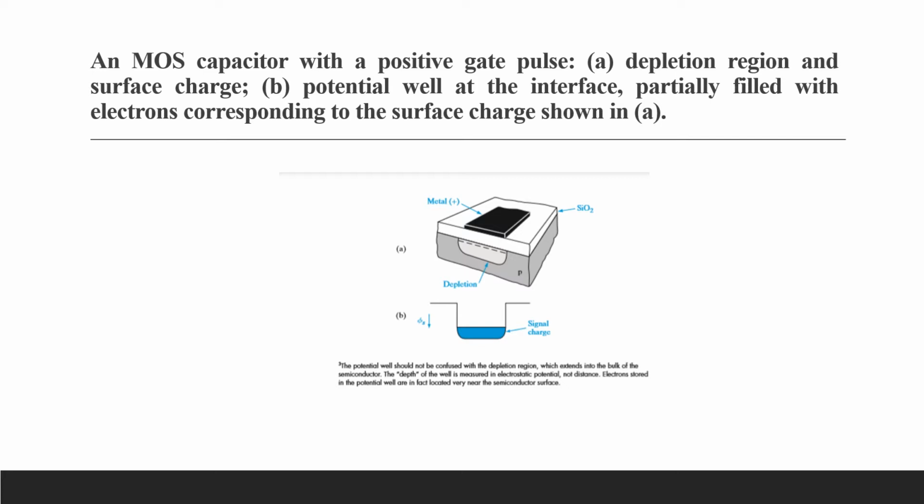So you must understand this, that the basis of CCD is the dynamic storage and withdrawal of charge in a series of MOS transistors. Thus, we must begin by extending the MOS transistor, which we have discussed in chapter number 6 about field effect transistor. Now here you can see a figure which shows a MOS capacitor on a p-type substrate with a large positive gate pulse applied.